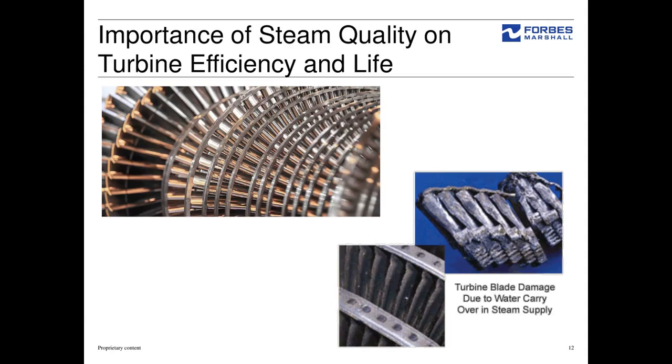So here you can see two photographs. On the left side you can see a new turbine with very highly polished and well profiled steam turbine blades, and if there is a carryover of water droplets into this turbine, there can be huge damage. You can see some of the photographs where turbine blades are actually eroded like shot blasting,